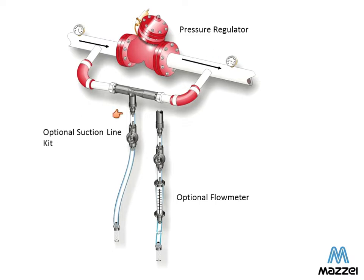This is a natural place where you can install a Venturi type injector on a bypass around this already existing pressure drop. The injector being installed in parallel with this pressure regulator will see at its inlet the same pressure that the pressure regulator sees upstream, and the injector's outlet will see the outlet pressure that the pressure regulator sees.